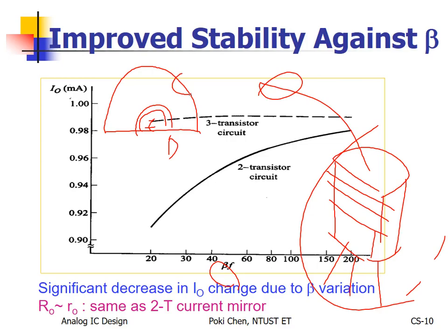Especially, I would like to point out something maybe you never learned from your microelectronics. For NPN or PNP, I don't care. Emitter needs to emit majority carriers, so it is highly doped. Collector is used to collect all the carriers emitted from the emitter, so it doesn't need to be highly doped. Usually it is very lightly doped.